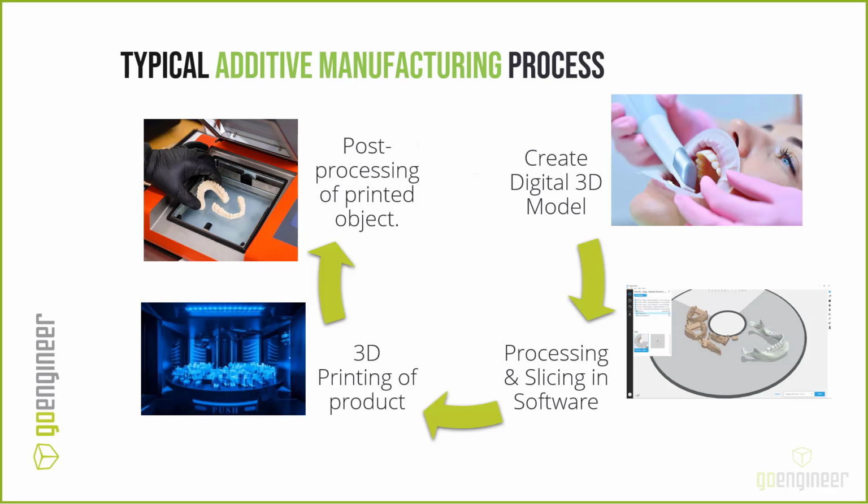Regardless of what additive manufacturing technology you're looking at, typically they all share the same basic process or workflow where you can create a digital 3D model. Here you can see a patient having her mouth scanned with an intraoral scanner, but it doesn't matter where the model comes from. Of course, the topic of today is SolidWorks, so it's very easy to generate models in SolidWorks and then export them into the next step, which is the processing and slicing in software.